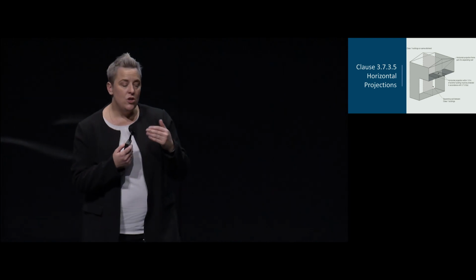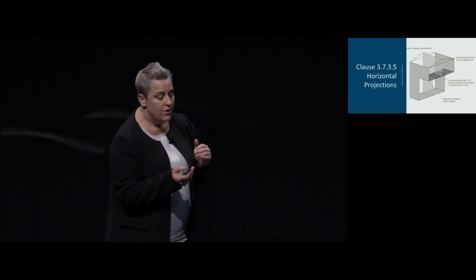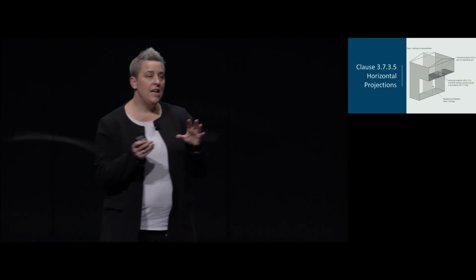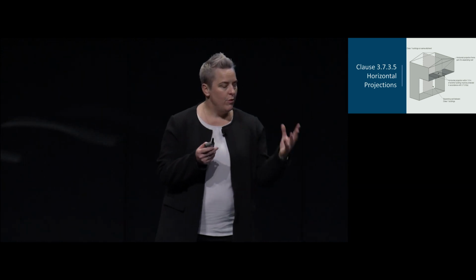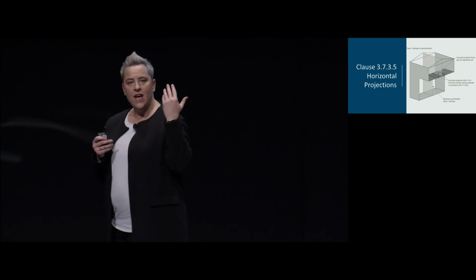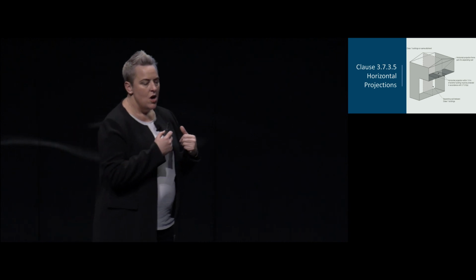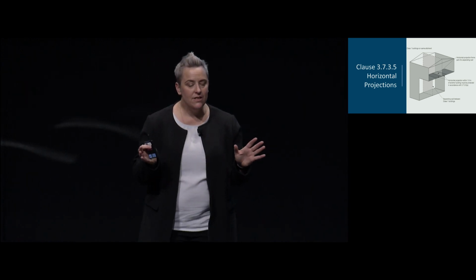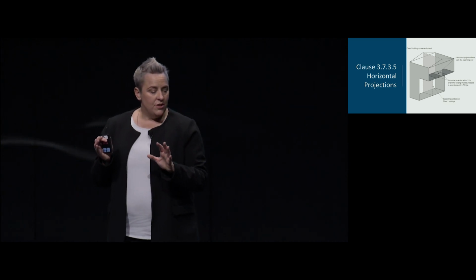So there's now a new deemed to satisfy provisions to provide a new part to deal with the horizontal projections, filling in that gap. So once again, it's part of that project where the ABCB have looked at common performance solutions and seen whether or not they can adopt that into the code, and they've done that in this instance. So the provisions require that the projection within 1.8 metres of the separating wall, and there are a few options for compliance.